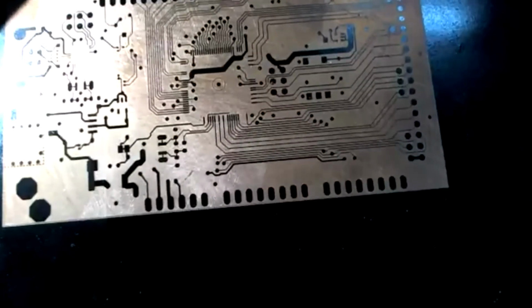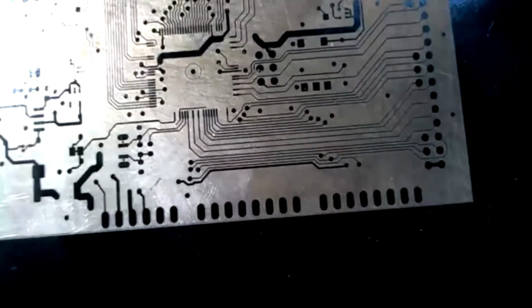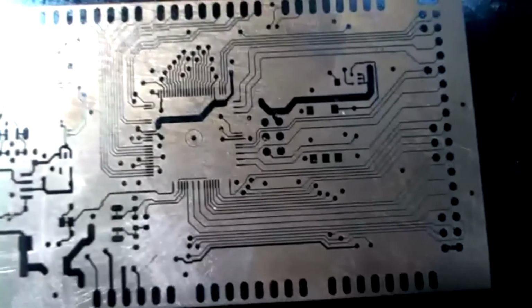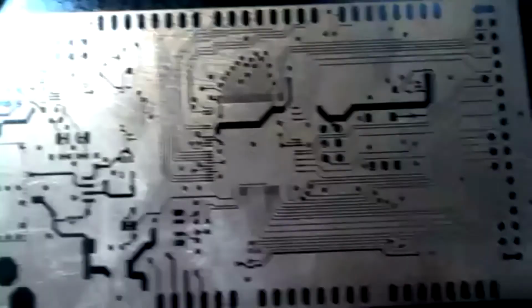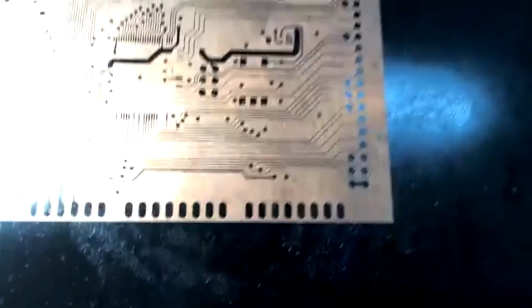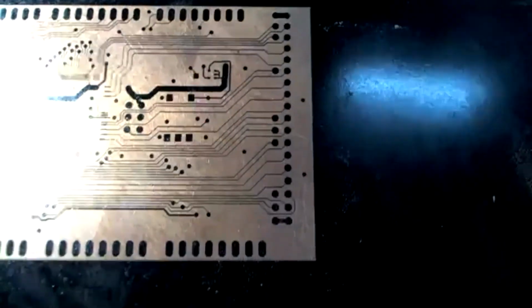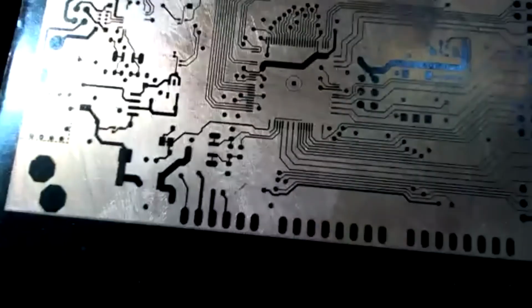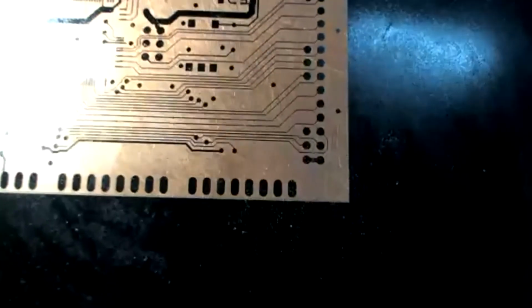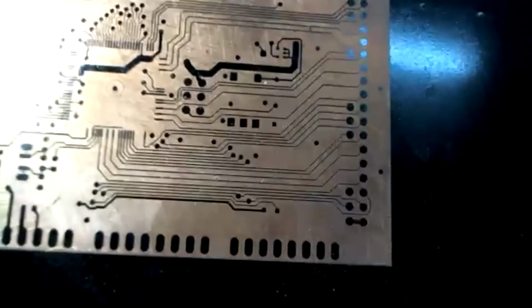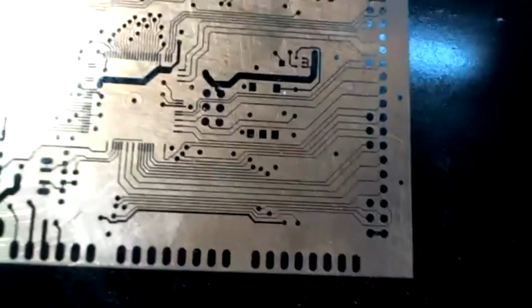Traces. This is the ATmega IC which I showed on the circuit. So this is the power IC legs, and these are the traces which are developed. These are the vias, so this is top and bottom. These are the measurement vias, the corner vias, and in between, in these vias, we have to make holes. With these holes, they have to come down. In the bottom layer, once you develop the bottom, you can make the vias.